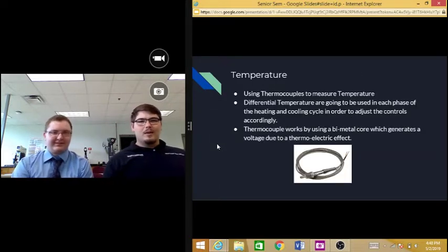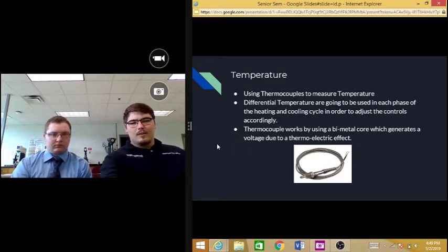For the temperature sensors, we used two different types. We used a thermistor, and we used two of these temperature and humidity sensors for the actual application of this. We were pulling temperature readings from the beginning, the middle, and the end of the fan coil, and we would use that for the psychrometrics in order to figure out if there's a loss of temperature, what exactly the correlation is between what we're doing and the actual output, and then we could trend it into the database and figure out long-term effects of what the controls are doing.